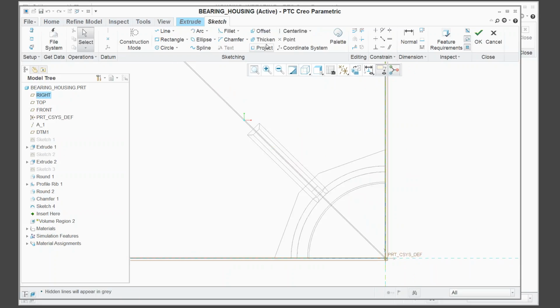All I'm going to do is sketch a quarter of an arc. Let's see. I can use the center arc so we know where the center is. So our arc would go something like that, and this should be a closed volume for this feature. So we just close this up, and this is just like sketching anything else in Creo. It's really nothing terribly complicated. And its radius should probably be about 0.8. Something like that. Now a little bigger than that. Let's make that about 0.88. There we go. Okay.